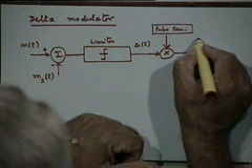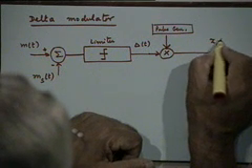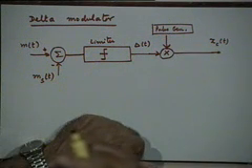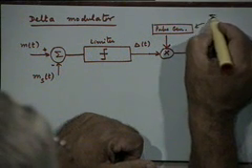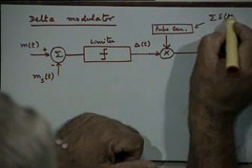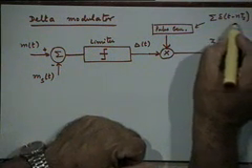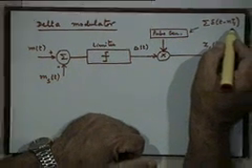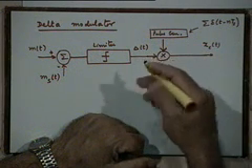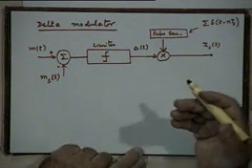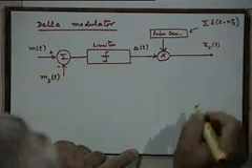So if you were to call the delta modulator output, let's say, x, your carrier is here, there is some carrier x sub c(t). This pulse generator gives you a train of pulses like this, impulses δ(t - nTs). So there is a pulse rate involved, which is 1 by Ts, right? The pulse generator is producing these impulses at a rate of 1 by Ts,